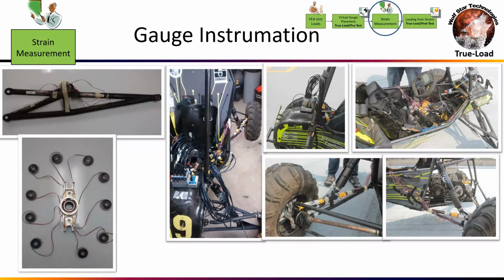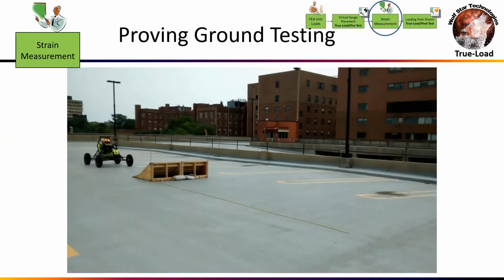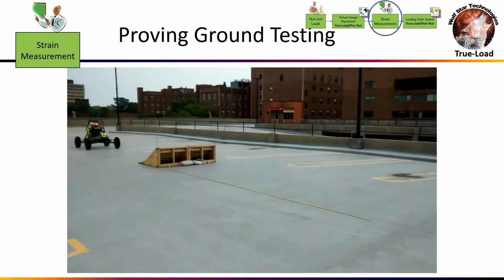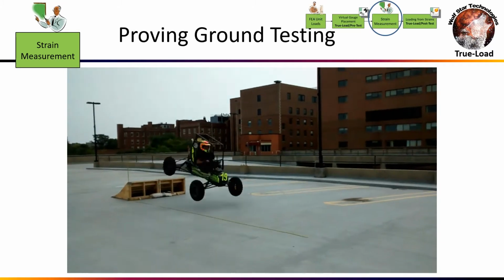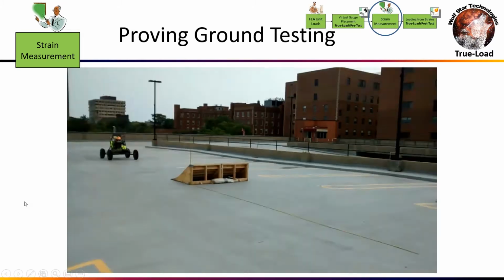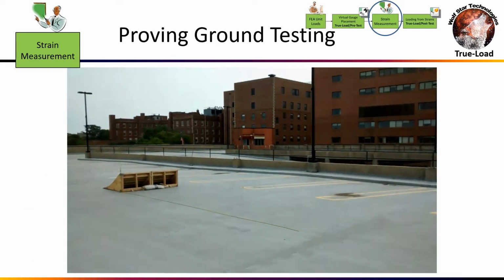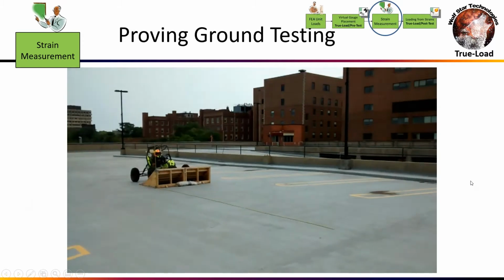So over the summer, with some coaching from me and some other folks, they basically figured out how to do strain gauging and how to do data acquisition, and they wired up this Baja car and got it all going, and they did the true load modeling, and they even went off and built jumps. And so here's a jump that they built, and we set up the parking structure at the university as a proving ground. So we're collecting data going over this jump here, and then we did max brakes and hard turns in the parking structure as well, and we're collecting data.